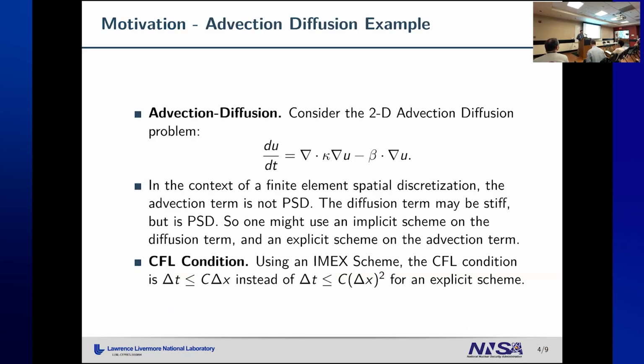To give even more context, I mentioned at the outset that this is a project within a project. The main project that I've been working on at LLNL is topology optimization, specifically in the context of heat transfer. One of the constraints in this optimization problem ends up becoming an advection-diffusion equation. In this context, we wanted to use an IMEX scheme for the time integration. Since we wanted to use MFEM, we thought, let's think of a new framework for implementation of IMEX schemes into MFEM. While you can implement IMEX schemes in the current version of MFEM, the framework that I'm going to be discussing today makes it a lot nicer.